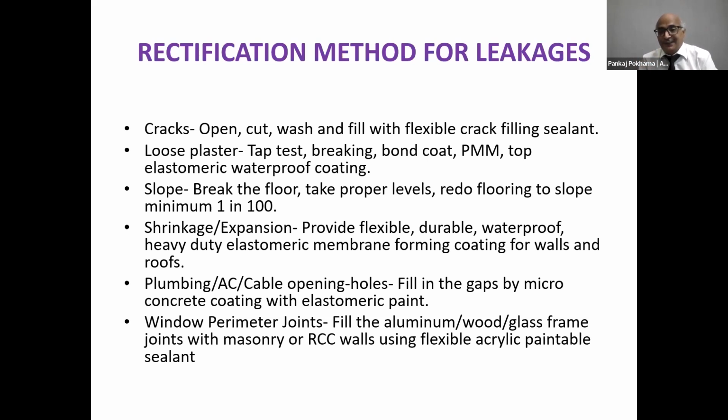After washing it, you have to fill it with flexible sealant. The flexible crack fill sealant is in acrylic form, so it comes in white color. It can also be tinted to the color of choice so that it can match the existing wall color shade also. When you fill it with that sealant and it dries, it becomes a flexible sealant.